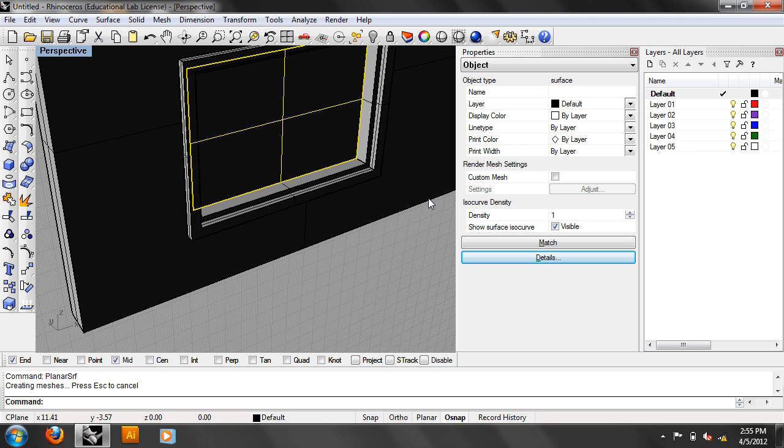When you make glass, guys, I would just model it as a single plane. Just take a rectangle or even draw a plane at the midpoint of your window frame, and that's your window. And as I said frequently, in computers, you get copies for free. So if you have windows that are repetitive, which in most cases you do, just make one of these things and then copy it to the rest. Don't make each one. It sounds stupid, but I see students do this all the time.